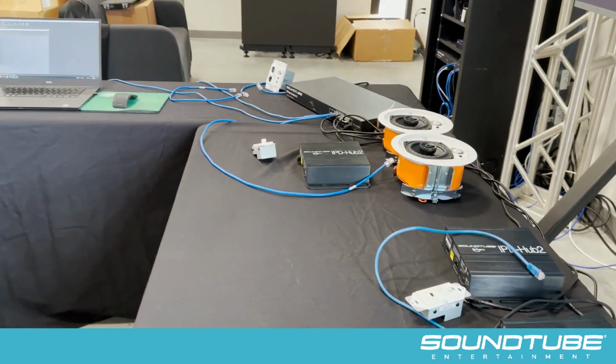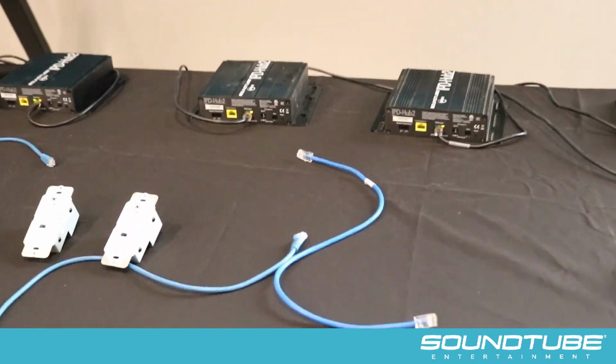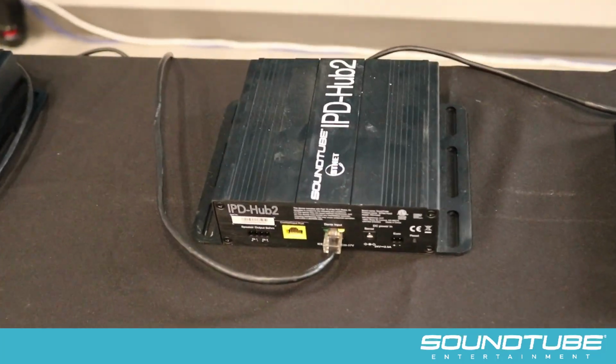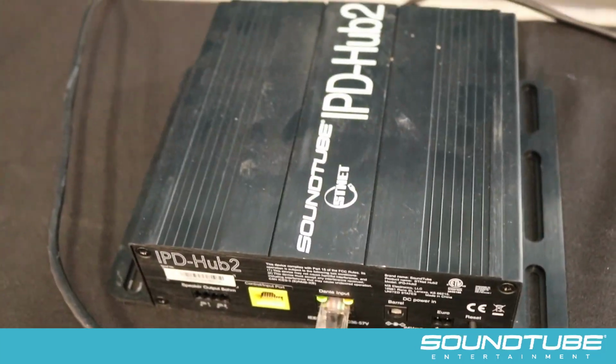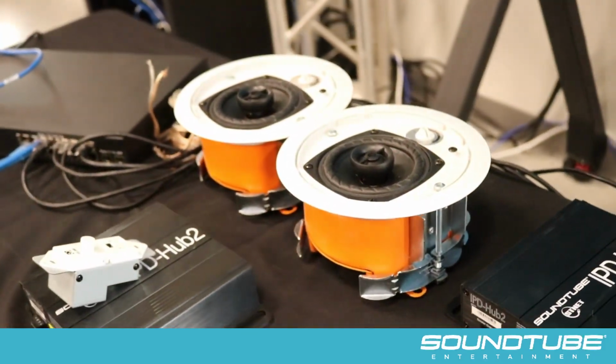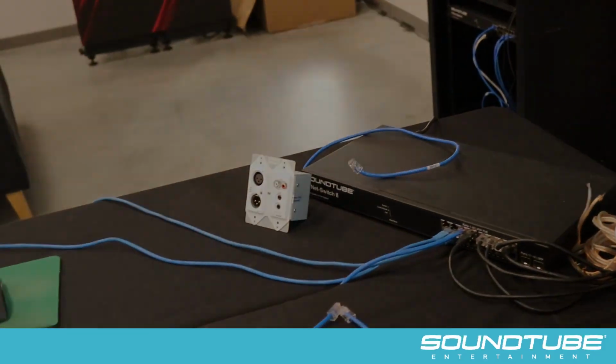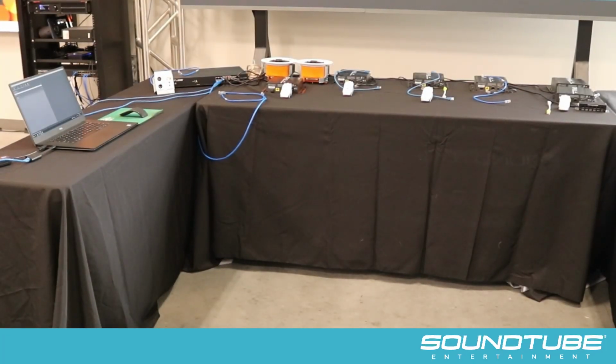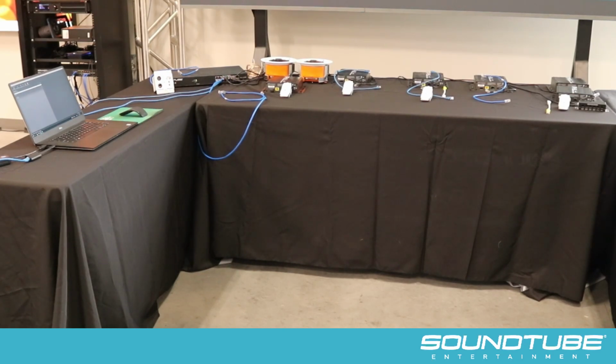volume control. The dining area zone contains an additional IPD-Hub 2 amplifier, as well as an IPD-Hub 2 extender box, which is paired with an RDL Format A sender for local audio input throughout the space. The private event room also contains an RDL Format A sender for local audio input in that space. The system as a whole is tied together through Dante infrastructure.